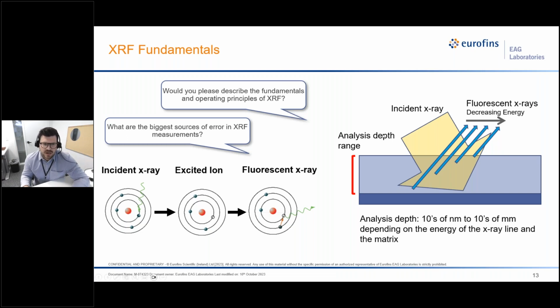In our other figure, on the right, we show the primary beam hitting the sample. The X-ray fluorescence that is generated is going to come from varying thicknesses within the sample. And as a result, this is our first possible source of error. The thing to note here is that the higher the energy of the fluorescence X-ray generated, the greater the escape depth of that X-ray from the sample. This is a huge reason why samples being analyzed by XRF need to be homogeneous in order for us to get that greatest degree of accuracy possible.